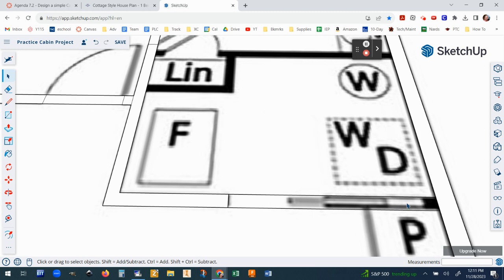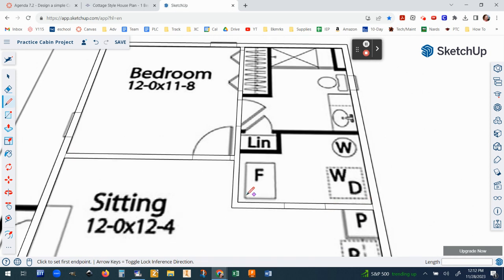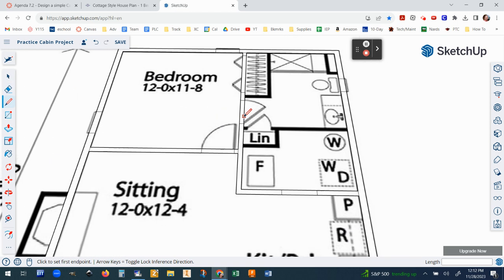Now this is a pocket door, okay? So from here over to the right is kind of like an open hollow wall, and then the pocket door slides into it. So what I'm going to do is make my wall opening here, about where that hollow part ends. That's the end of the doors on that wall, so I can stop deleting the faces. Let's move on to the rest of the walls in here, okay?